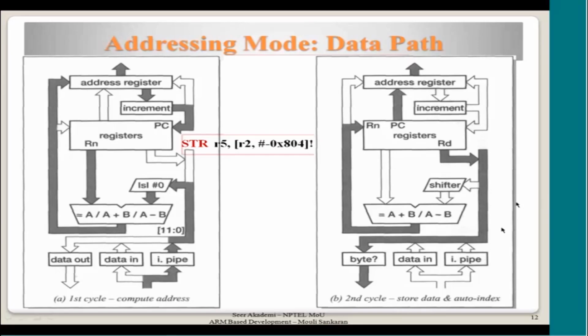Now you have a problem. I told you this particular path is used for writing the address, correct? Now I am saying that data also has to go through this. It cannot happen together. Now is the catch. Understand this. When a particular value is loaded from memory, in that cycle the value comes and sits in data in. It is not taken inside because there will be a delay of introducing so much, if it has to be done in a clock.